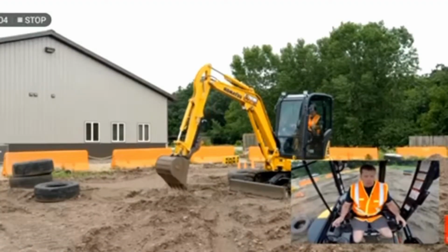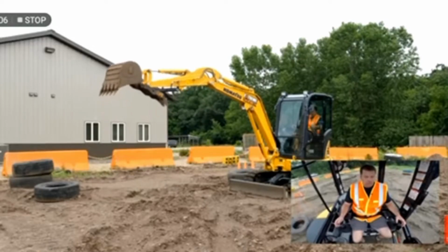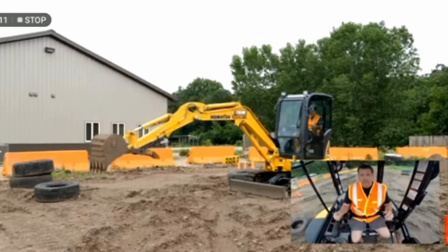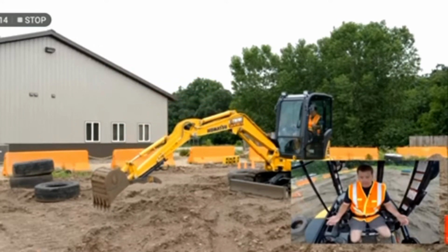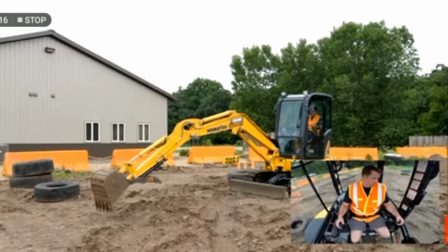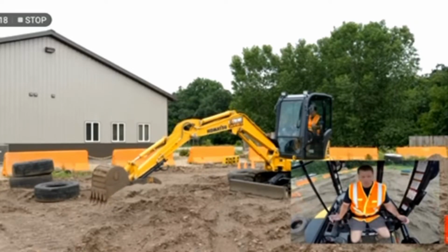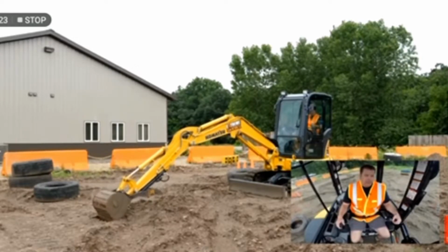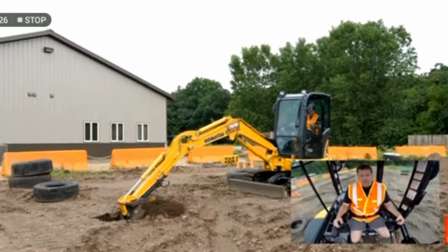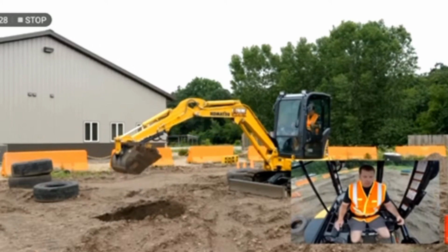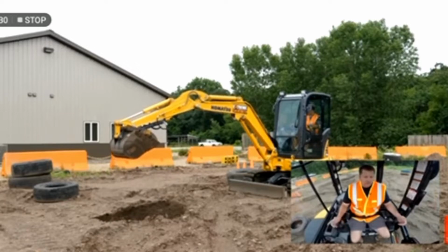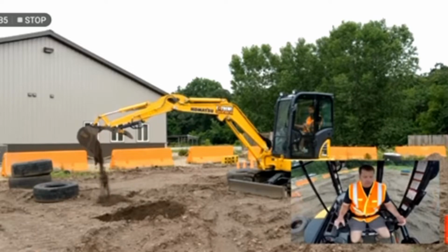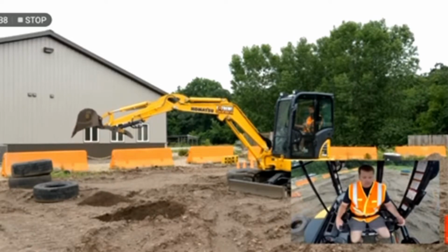I'm going to extend that out. Again, we start all the way out, so I've got the stick extended. You bring it down towards the ground, stopping a few feet. This is where you want to make sure your teeth are relatively out a little bit, so right about there. Put it down in the ground. Once it's in, I'm just going to go right hand to the left, curl that bucket all the way in. Raise it up, and then I can spin left or right to dump right in there. That's fully extended.